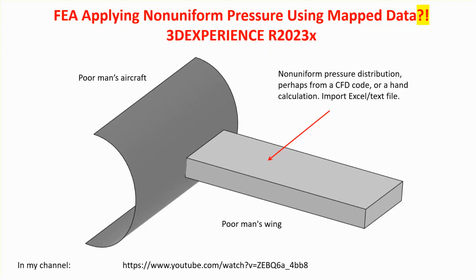Unfortunately, those things are not directly applicable to the 3D Experience platform, and therefore I decided to go through a very simple rudimentary problem, where the pressure distribution is applied by the user and it's non-uniform. Incidentally, I do have a video tutorial doing more or less the same thing in the CATIA program. CATIA's native FEA solver is actually the Elfini program, whereas in the 3D Experience, it is the Abaqus.